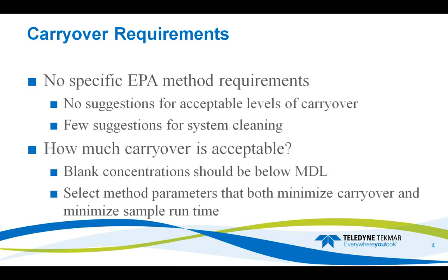So, first place to start with is how much carryover is too much. Well, if we go to our EPA methods, we find that there are no specific requirements for carryover. There are really no suggestions for acceptable levels of carryover, and there are very few suggestions for what constitutes adequate system cleaning. So, how much carryover is acceptable? Well, we like to suggest that blank concentrations run after high concentration standards should be at least below MRL or a method detection limit.